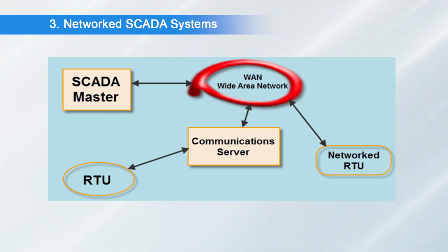This third generation SCADA system uses programmable logic controllers for monitoring and adjusting routine operations, flagging operators only in the case of a major decision requirement. Network SCADA architecture is the current crop of architecture we mostly use today in almost all the big industries.